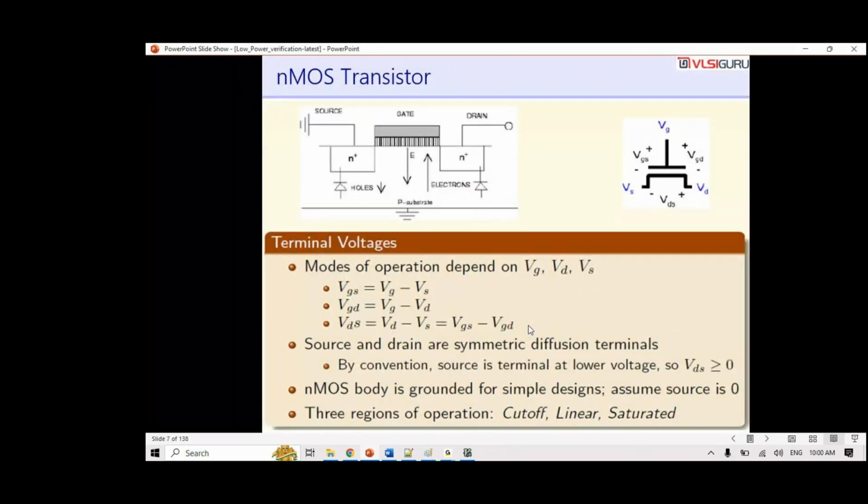Okay, so for our convenience we'll take an example of NMOS transistor. You would be aware that NMOS has a P substrate with n type of doping for source and the drain. Then it has got an oxide, then it has got a polysilicon, which is connected through the gate. Then you see in NMOS, you would be aware that source is connected to the ground and drain is connected to the voltage supply. And you would be aware that as you apply voltage here, what happens when you're applying a positive voltage? Means you are bringing the voltage difference between these two.